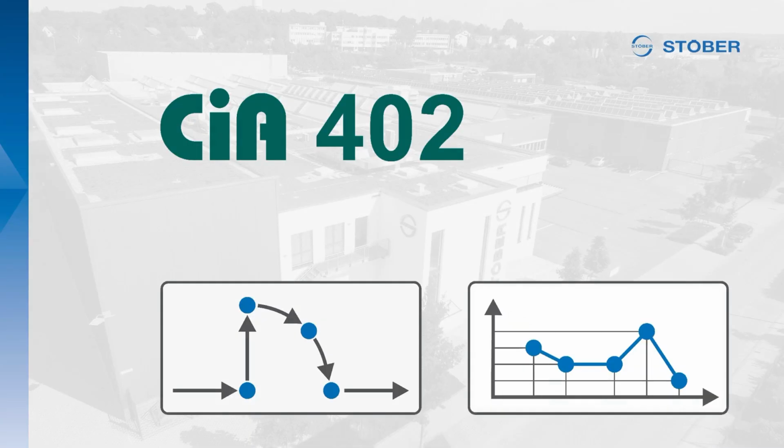With the control-based operating data of the CiA 402, you can implement applications with synchronized cyclic set point specification via a motion control controller. On the other hand, the drive-based operating data of the CiA 402 provide complete motion calculation and execution within the drive itself. In this process, the set points for position, speed, and torque are implemented into motion accurately and precisely.